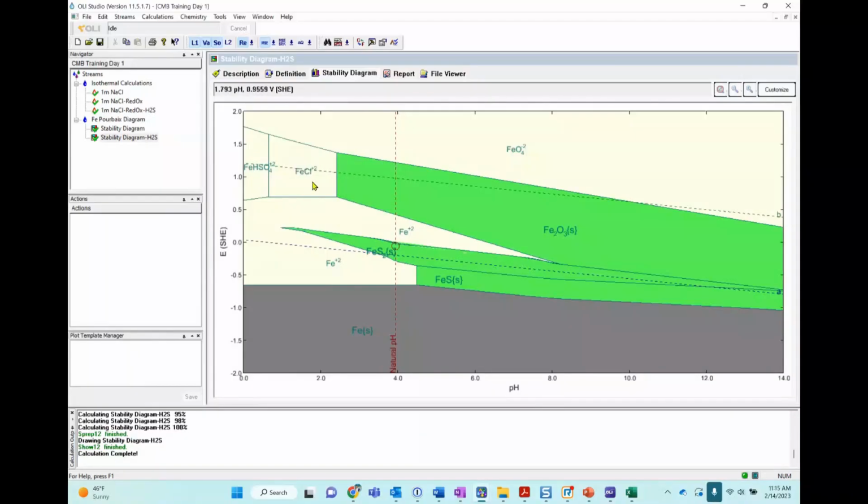But if you're working with corrosion rates, from a metallurgist point of view, these pH values here are not relevant, right? Nor the complexes, because you always want to operate above maybe 4, 5, 6 pH, where carbon steel is more corrosion resistant, let's call it. Because if you're operating at these pH values, carbon steel is just useless, right?